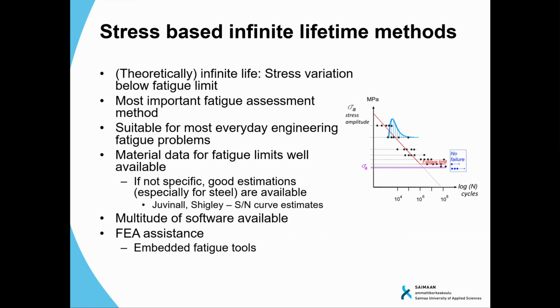Also, as it has been investigated quite extensively, there are different kinds of software available for infinite lifetime calculation, and also there is the finite element method that you can use. There are even embedded tools in the finite element software that you can use for fatigue assessment. But of course, when using those, you will need to know what the basics of fatigue are, what the loadings are, what the function of the Wöhler curve is. Otherwise, you don't benefit much from the result if you don't understand what the machine is doing.